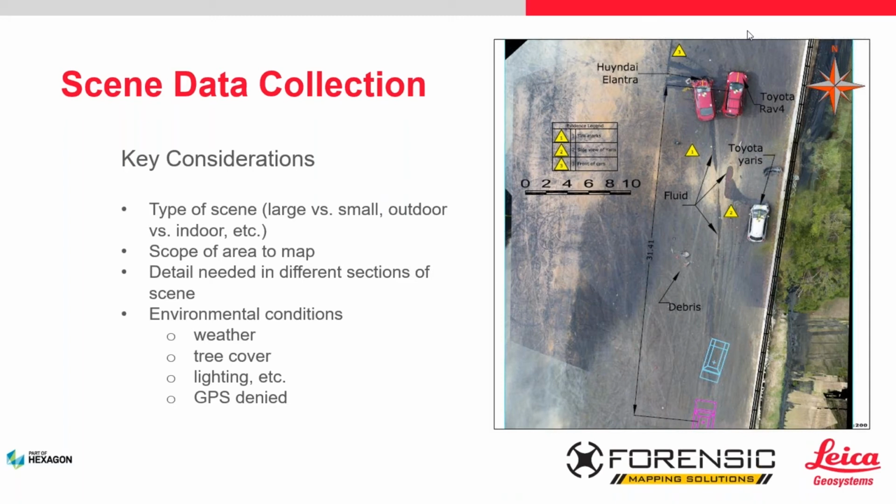Okay. The other thing to think about too is that we're also used to mapping, whether it's with a total station or what's called RTK GPS or GNSS, which is a network corrected GPS measurement. So the accuracy is a couple hundredths of a foot. As we all know, a regular GPS is 3 to 5 meters or 10 to 15 feet at its best. So that's why we need to have the corrected GPS. And those are other tools that you could use at your scene. And all of this can be incorporated into